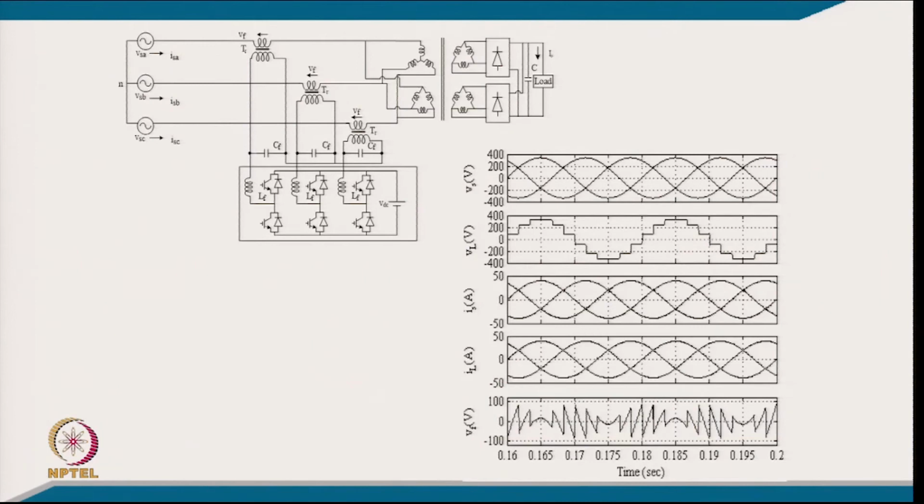So, this is the typical circuit. Here we have a load which is a 12 pulse converter, an isolated converter with star delta and delta delta, and both converters are connected in parallel with the capacitive load, and the voltage and load are given. Now, if we put an injection of voltage with the series active power filter, then by appropriate injection of the voltage we can maintain the supply line current balanced sinusoidal at unity power factor, in phase with the voltage.